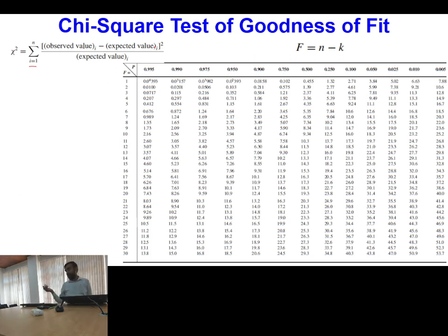Okay, so from theoretical understanding, say you know the value of flow rate in some pipe and heat transfer is taking place. Theoretically you can have some idea, some expected value of the heat transfer coefficient you will be getting. And the same heat transfer coefficient you can also calculate from the observed value. So if you have to test whether your expected and observed values have a good match or not, then you can utilize the chi-square test for goodness of fit.